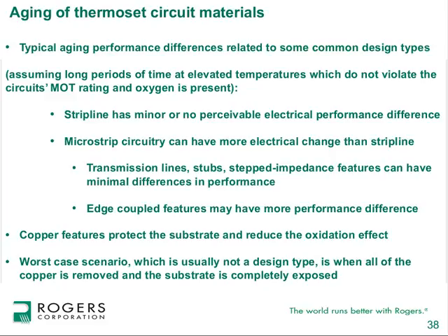And the reason why is because now you have these conductors with a space between them, and there's fields in there, and those fields are using the exposed substrate that has possibly oxidized over time with accelerated temperatures. So the bottom line is the copper does protect the substrate, and when you have designs where the copper is not protecting the substrate, that's more susceptible to some changes. Now, worst-case scenario is etching all the copper off and then doing testing, which we've done on numerous occasions.